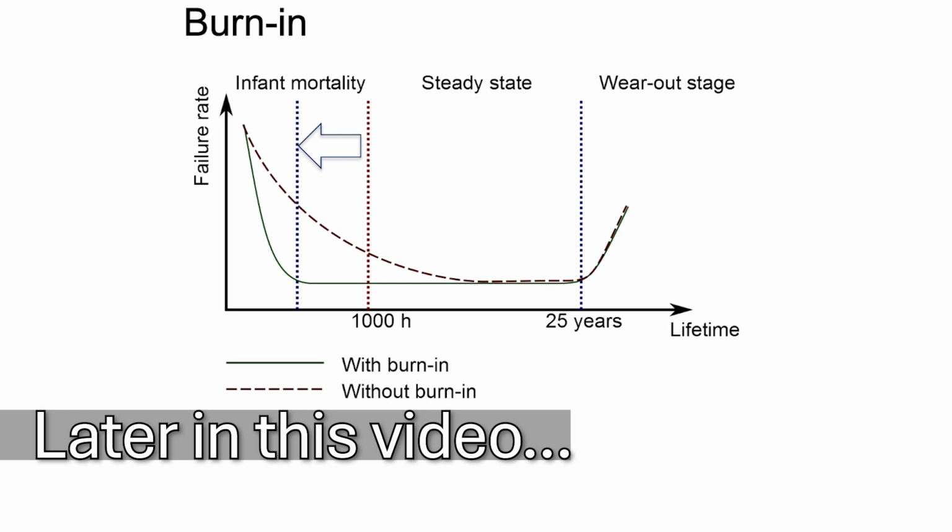We plug it in the application and it works, but after just a few hours, this weakness is going to degrade quickly, and we have, for example, a developing short in the gate oxide that only develops during the operation.